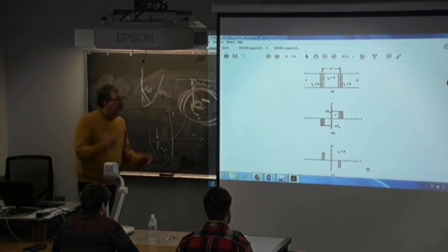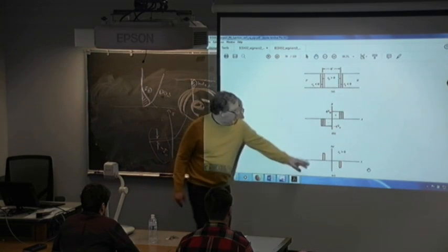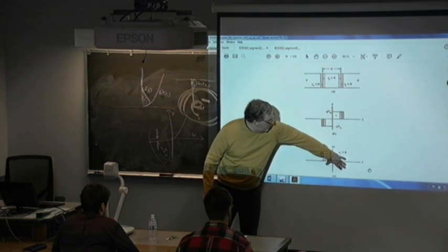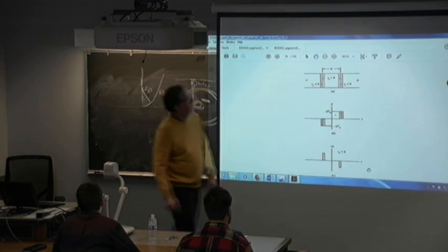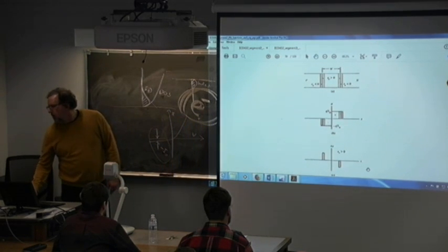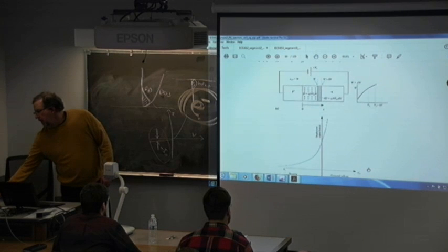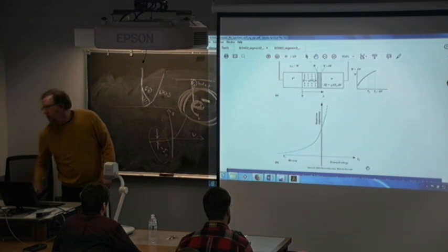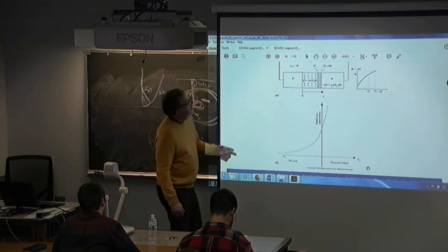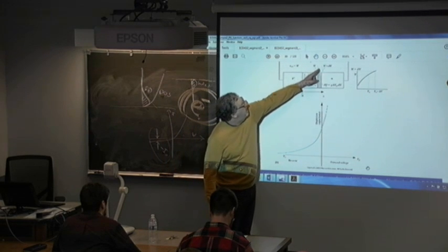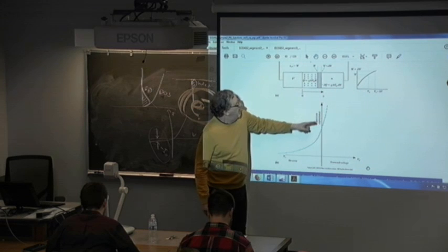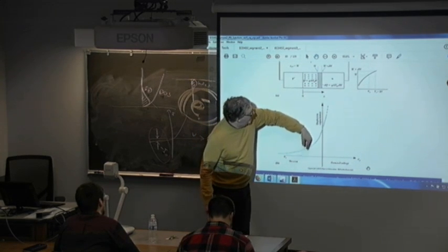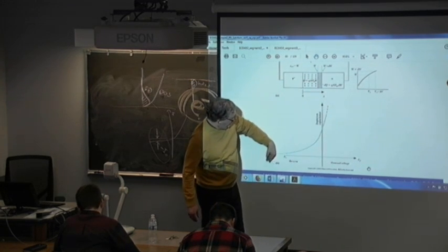Delta Q over delta V is the capacitance. So this is the Q, the change in Q as a function of the small voltage, right? So that's capacitance. And so as you apply a bias, the depletion region goes from W to W plus dW, extends out, and so then you can see the depletion capacitance follows this kind of a formalism.